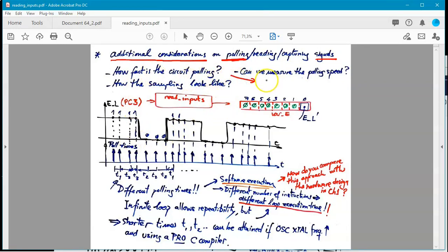You see, in that example, it took 30 microseconds, which means 33.3 kilohertz, and this kilohertz means 33.3 thousand samples per second. This is more or less the idea. You go and get samples from the enable active low at this speed. This is what it took to run the full loop. You have a loop, and then you go back to the beginning of the loop and do it again. And you do that all the time, so that here you have the reading function, so this instruction is executed at that speed. Very well.